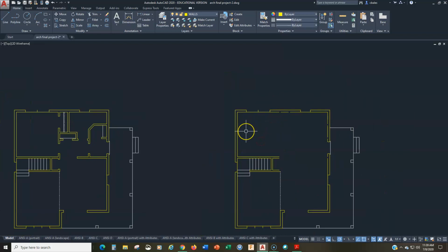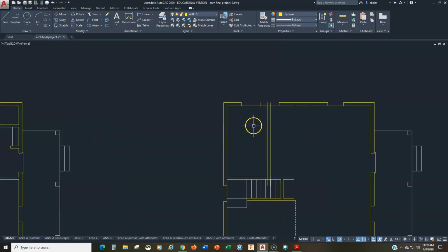Now the 7'6". So let's go offset 7'6", and remember I'm going from the outside wall over here. Okay, and then that is going to be the inside wall of the bedroom. All right, so then let's see, that would be offset 6.5 inches. And we go like so.